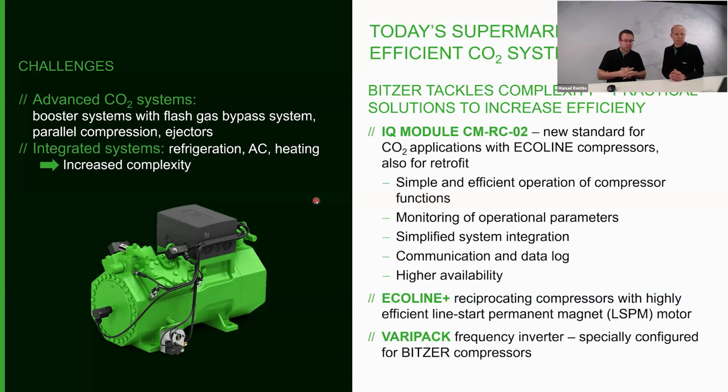You give us the 0 to 10 volt signal, and we give you the capacity you want to have. Secondly, we have some monitoring of the operation parameters, so the sensor values and so on we have in our data log as well. So you can communicate with the compressor, which makes it also a little bit easier.